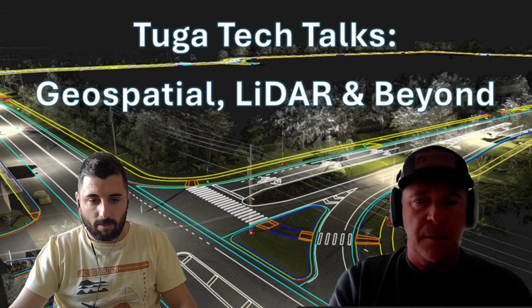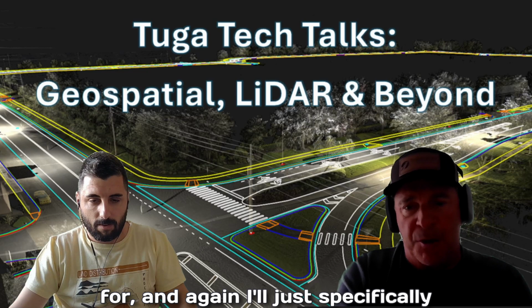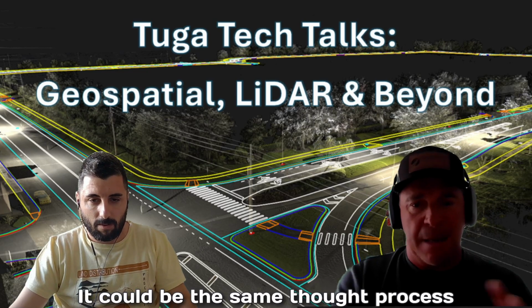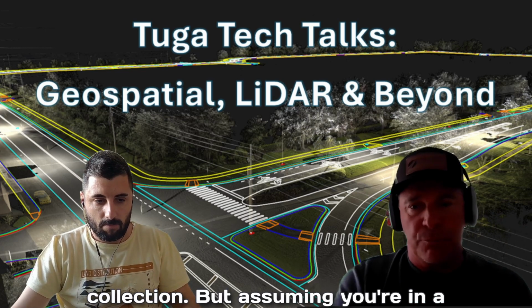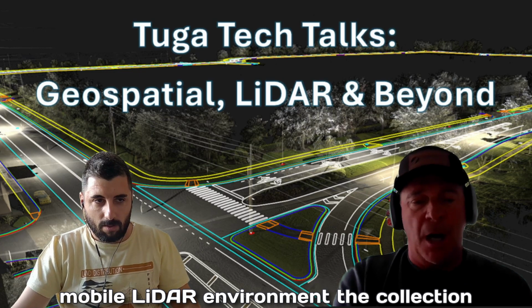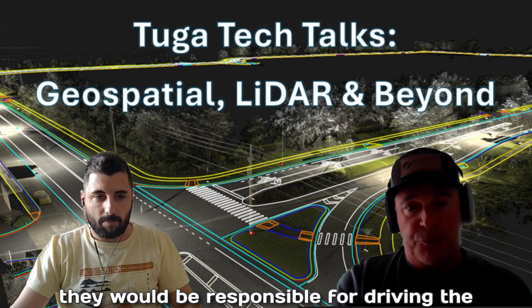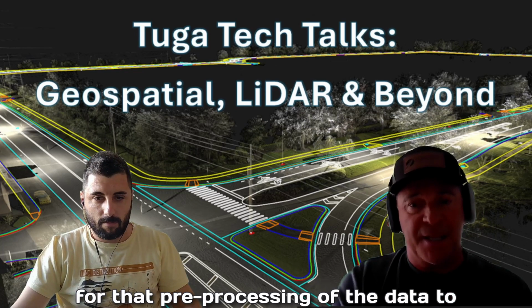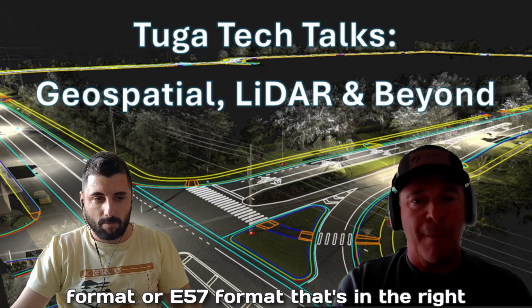For us, the field operation team was responsible for, and I'll speak specifically to mobile lidar, though the same thought process could be applied to other types of collection, targeting. They would be responsible for driving the site, and then for pre-processing the data to some standard LAS type format or E57 format that's in the right place.